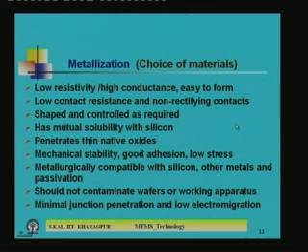If that metal film does not dissolve into the thin layer of silicon, you will not get proper contact. Mutual solubility with silicon means that at the interface the metal and silicon will form certain alloy, otherwise contact will not be proper. It is a very important aspect when you are selecting a material.